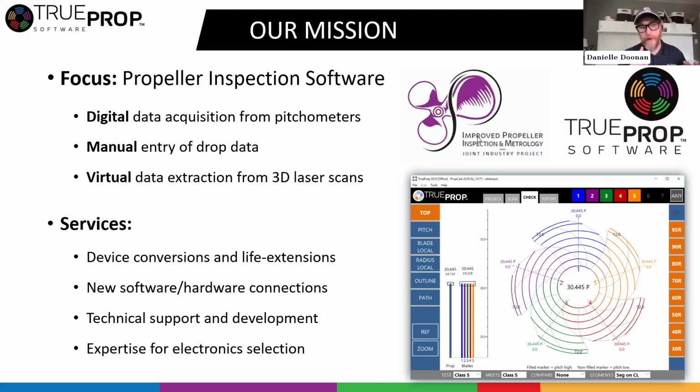We do replacement software, obviously; you add TrueProp to it and it's a new system. We also do hardware, helping people figure out what encoders or electronics they need. We offer electronics packages for people to build their own pitchometers. We just had a customer, Jerry at Northumberland Propeller in Nova Scotia, who built his own frame, bought an electronics kit from us, and has a fully operational digital pitchometer.